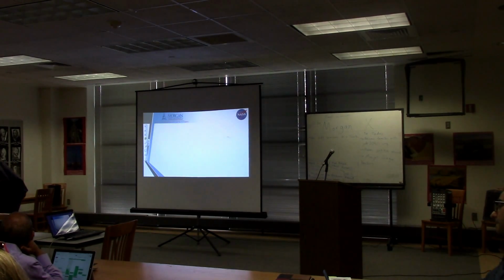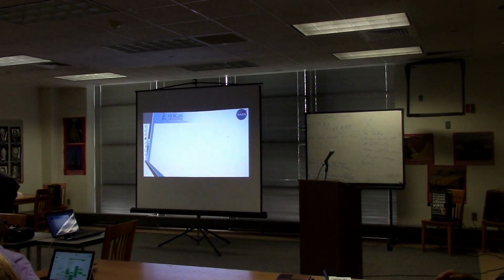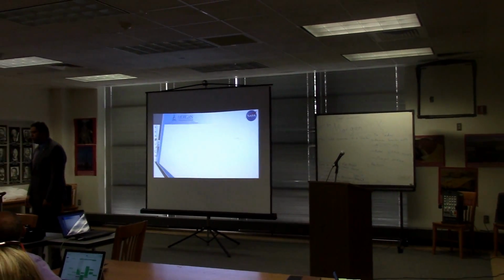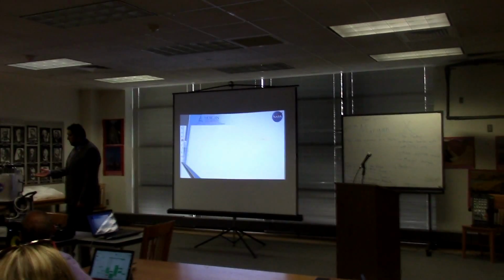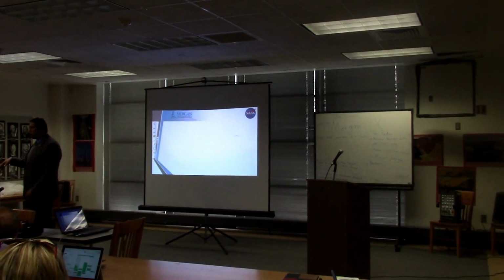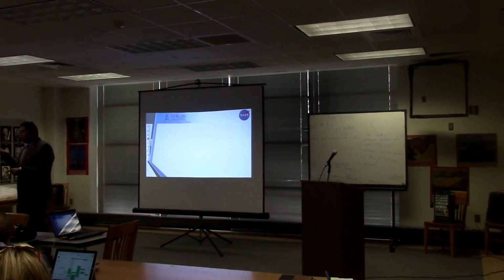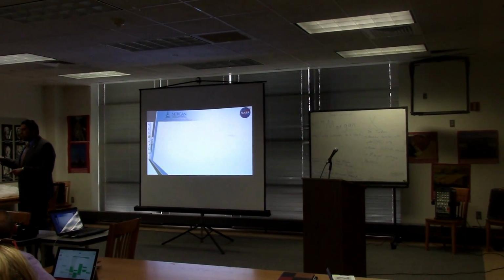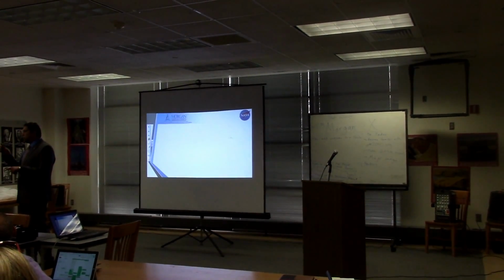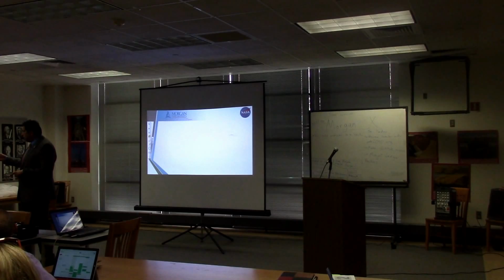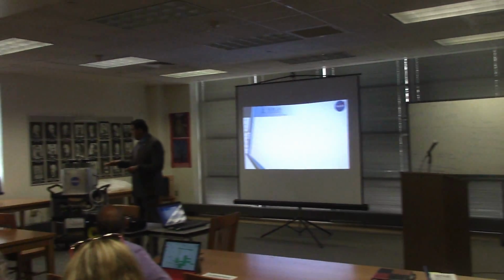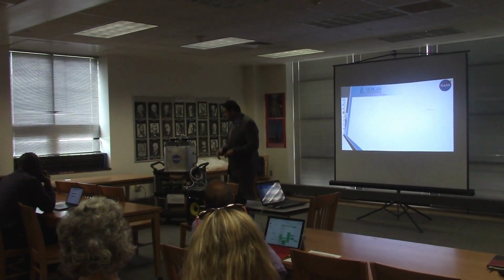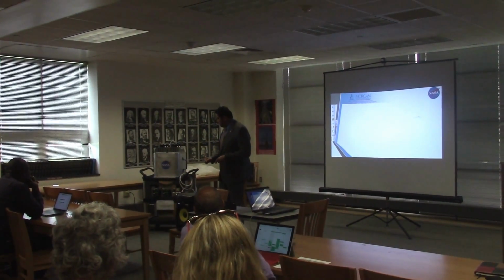I'm sorry, you can't see right here, but this temperature is starting at 27, and in a couple of seconds it will go down to like 15, 16. It's going to keep going down till it gets to the number that we set, and then it starts sending a square signal, depending on whatever frequency, to keep it at that temperature. It measures the temperature, goes up, starts the outside fan, measures again, goes to whatever temperature we want, and stops the system.